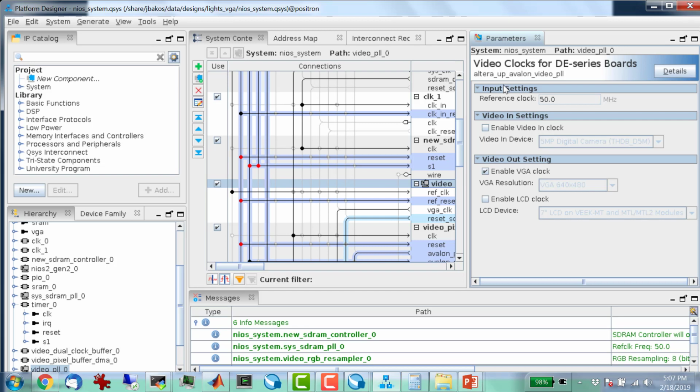Does that make sense? So that way you can look at how many cycles passed at one point and then check at another point and take the difference, and you'll know how many cycles have elapsed in that chunk of code. Right now we can't do that, but we can use the interval timer to get an idea of how many ticks have gone by. Great question. I was confused by that for like 10 years.